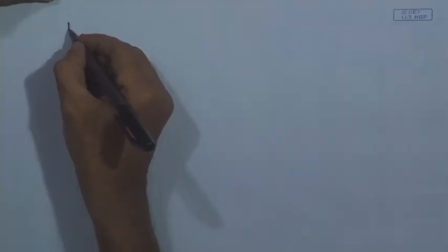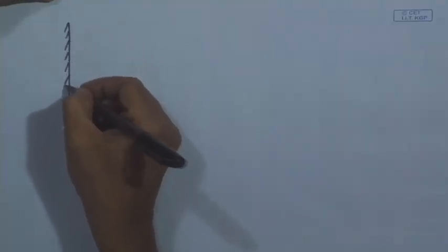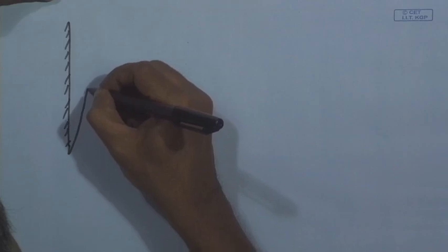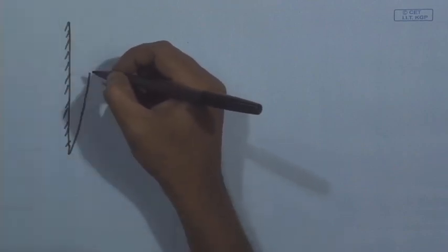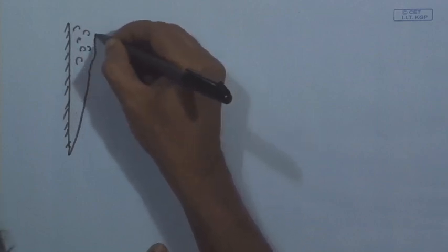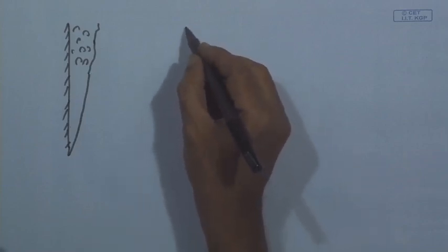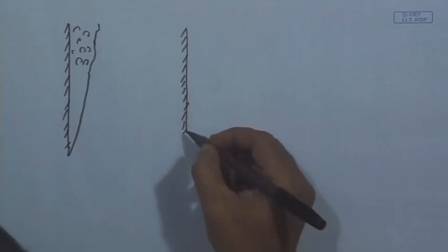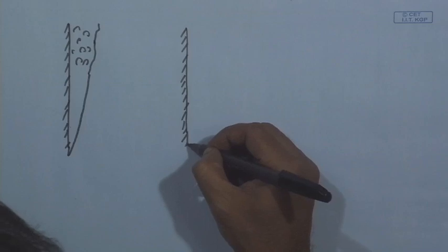Lastly, I want to say another thing, that the analysis which I have done has a lot of limitations. We are assuming that the vapor film is laminar, but after a certain distance the vapor film becomes turbulent. So, for this portion, turbulent analysis is important. Then in many cases we have assumed a smooth interface, but it is not like this.